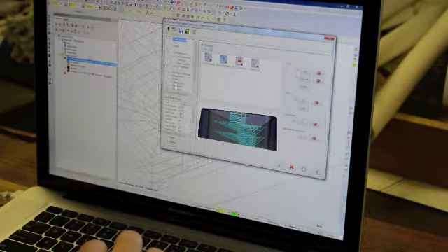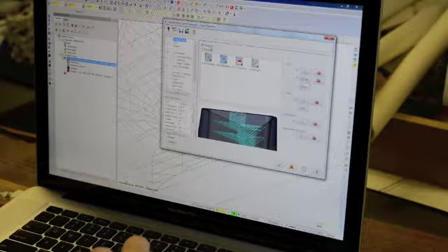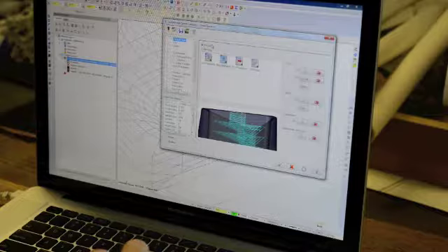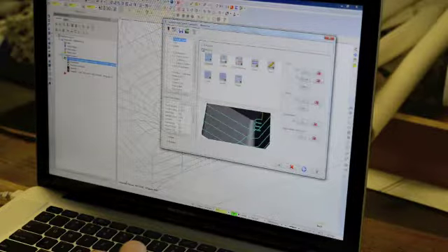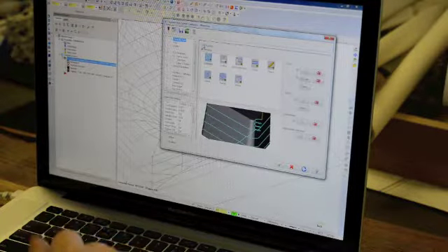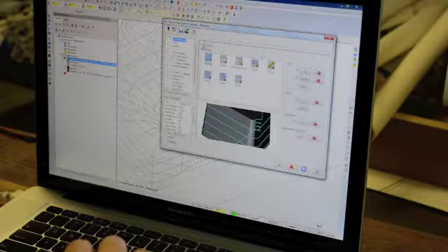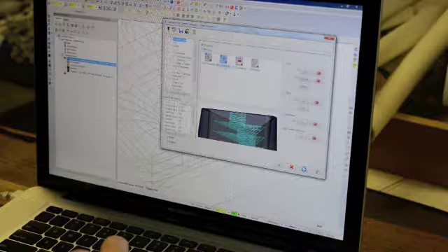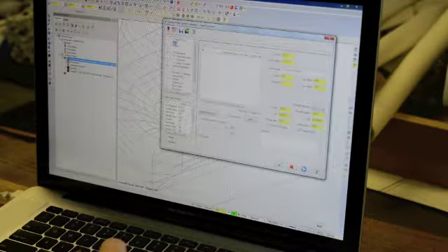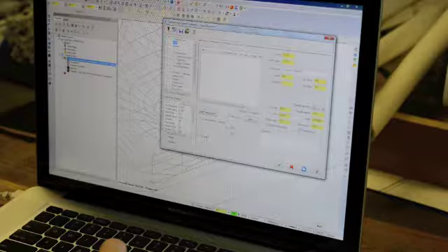So what we're going to do first, the way milling works is you'll do rough cuts, which you're just removing large portions of material, and then we'll do finish passes as another series of toolpaths, and that's what's going to give you whatever your finished surface is that you want. Okay, so rough, we're going to just do area clearance. We're going to pick a tool. Often it will give you some default, but it's usually not what you want.